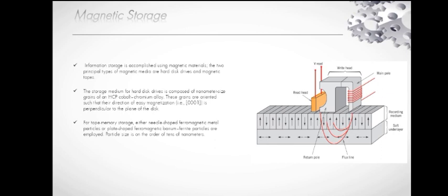So in this diagram, a hard disk drive that employs the perpendicular magnetic recording medium is shown, also shown are inductive write and magnetoresistive read heads. In essence, computer bytes, sound, or visual images in the form of electrical signals are recorded magnetically on very small segments of the magnetic storage medium. The heads are above and in close proximity to the magnetic medium by a self-generating air bearing as the medium passes beneath at relatively high rotational speed.